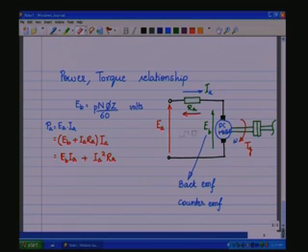In fact, EB IA is the power that is responsible for generating the mechanical power, or which goes in as the mechanical power. So, the mechanical power Pm will be EB into IA.